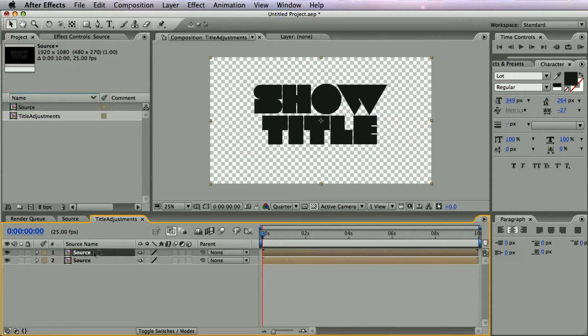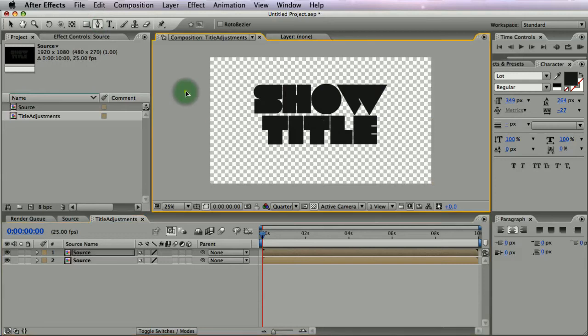layer. Take the pen tool and we'll draw a mask. Start from outside of composition, click and drag, then go to the opposite side, click and drag, come a bit lower, click and drag, come back here, click and drag, and connect your mask by clicking on the first point. So now switch back to selection tool and adjust the mask